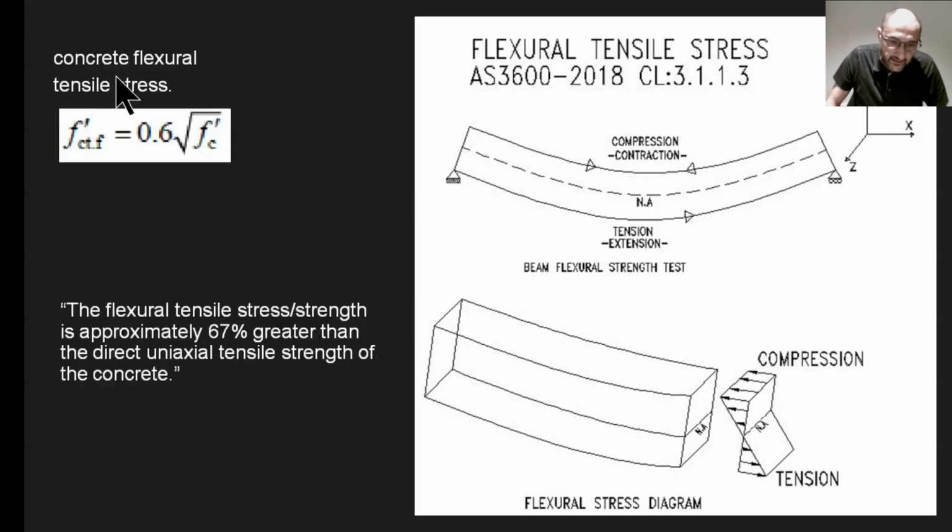For this reason, concrete would behave better as a beam or a slab element rather than, for example, a concrete stump taking direct uplift forces, or concrete columns or a pier subjected to high uniaxial tensile forces. It's a better element that takes flexural forces, or flexural compression and tension, which causes bending.